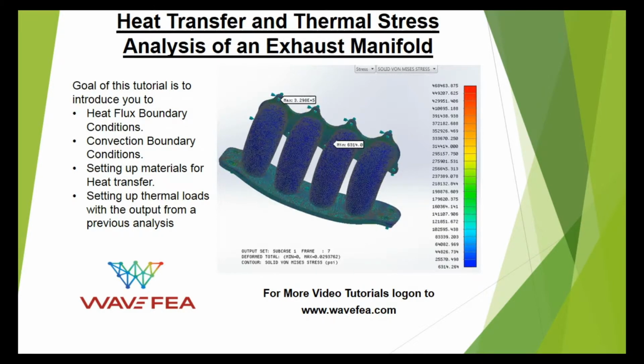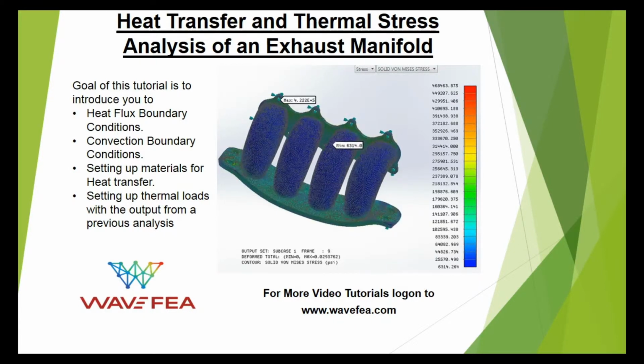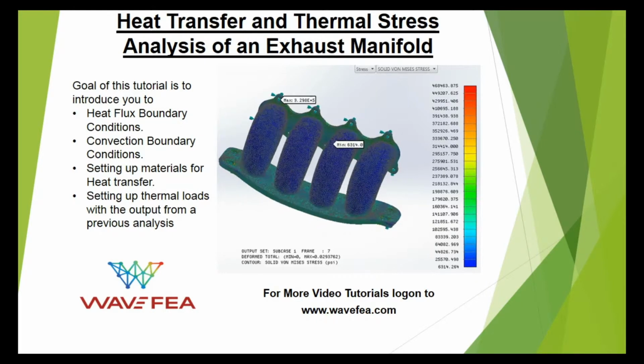The various topics that will be covered in this tutorial are heat flux boundary conditions, convection boundary conditions, setting up materials for heat transfer analysis, and setting up thermal loads with the output from previous analysis. We will be running the nonlinear steady-state heat transfer to get the temperature distribution for input, which serves as load from output in linear static analysis, which in turn will be used as thermal stress analysis.